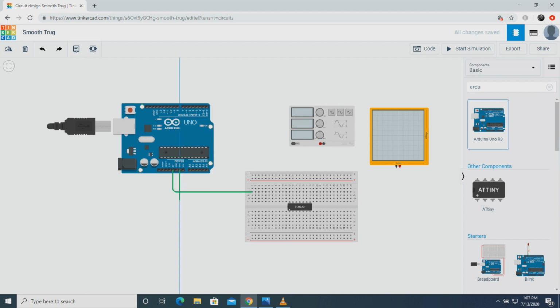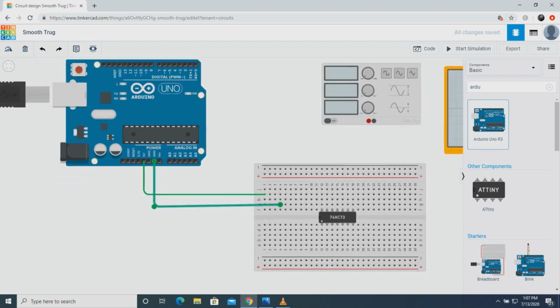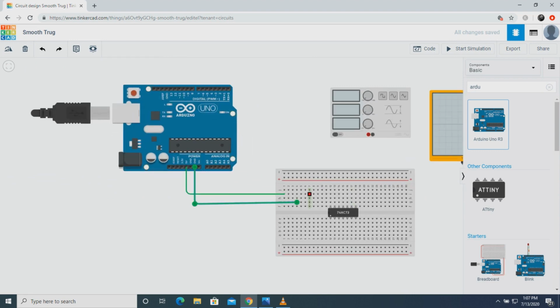So from that ground I'll be using another node here. Now this is the supply. I can short the voltage rails, positive VCC and the ground here. So what I will do right now is put a resistor to limit the currents, to control the currents in between these two nodes.